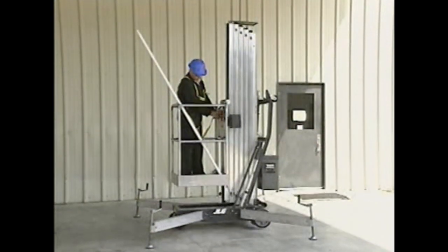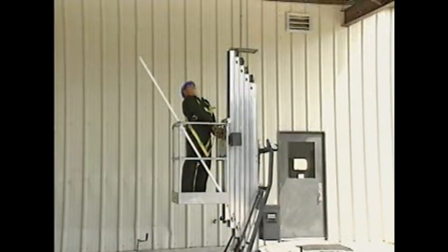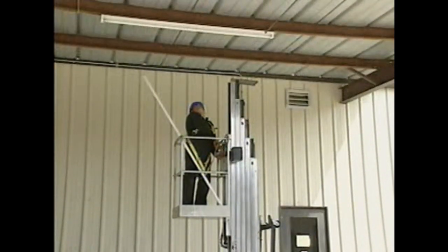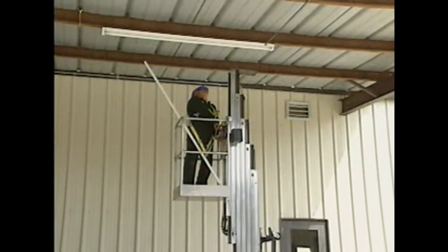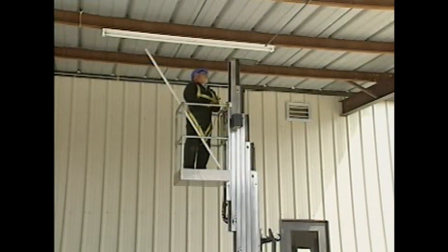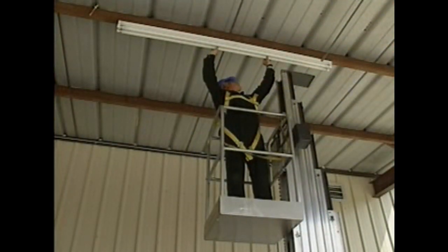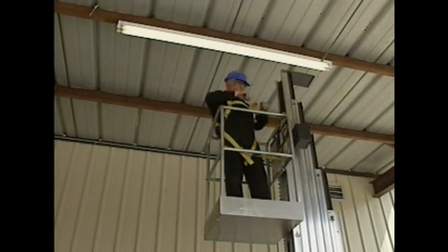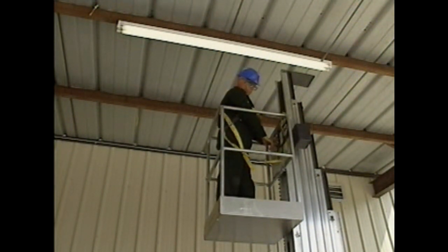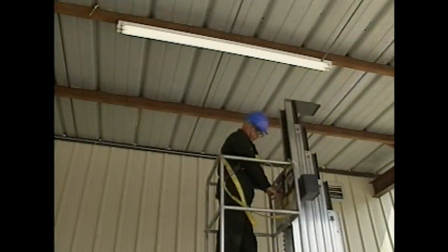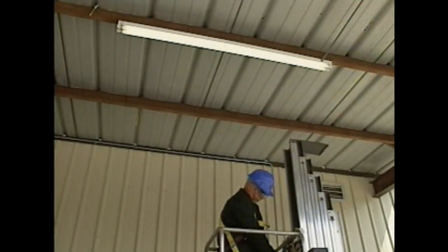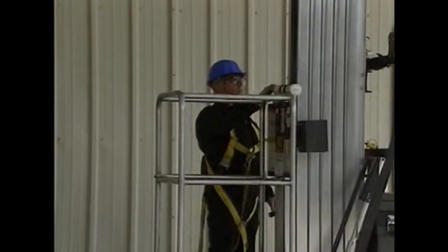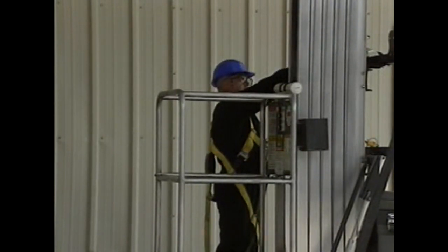As the scaffold moves upward, the worker is careful to keep his entire body within the caged area of the work platform. When he reaches the work area, he releases the up switch to stop the scaffold. He then performs the necessary work from the platform. When he's ready to come down, he presses the enabling switch and the down switch on the control panel. This lowers the scaffold to ground level. He then exits the caged work platform and sets the main switch to off.